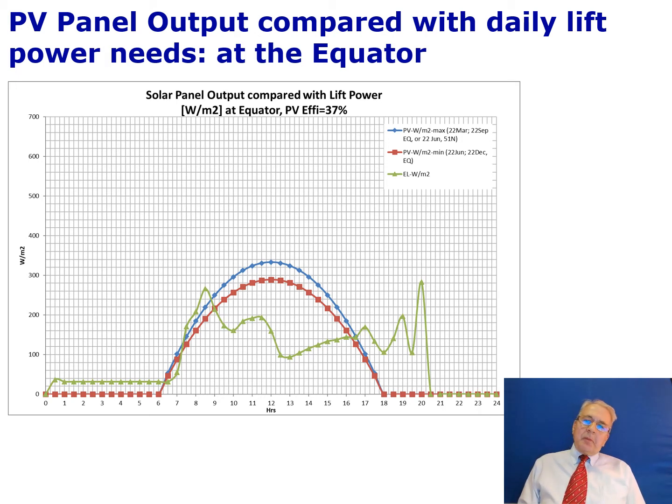Therefore, we'll propose a buffering battery bank to be charged from the solar panels to compensate and cover the energy needs. In that case, we'll not apply grid power supply. Based on the data which I illustrated in the diagram above, the required battery size was determined as 79 kilowatt-hour. The required solar panel area is then determined and given as 51 meter squared. And this is based on the minimum energy, the area which is below the red line.